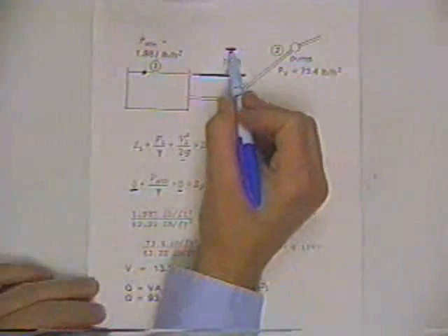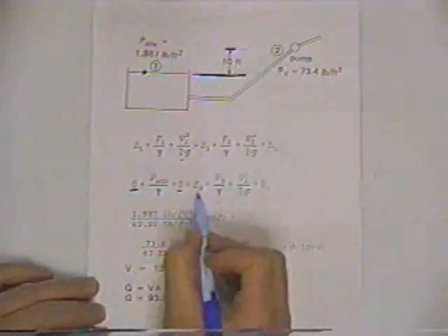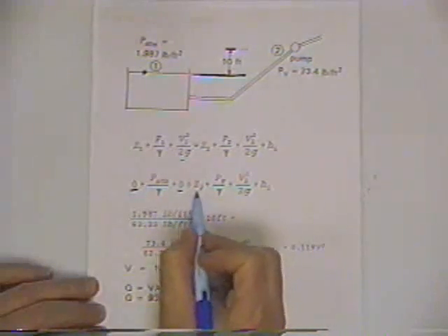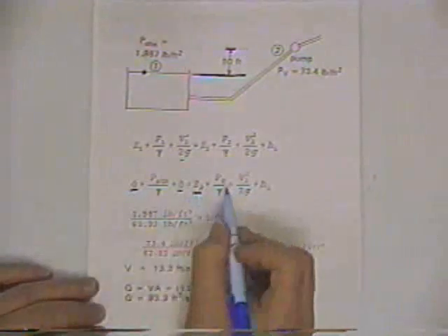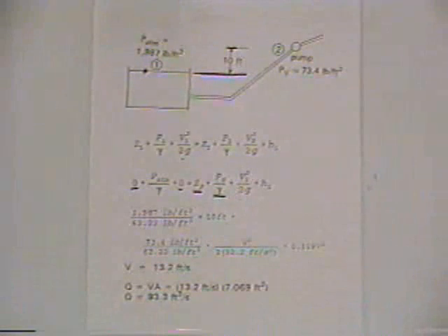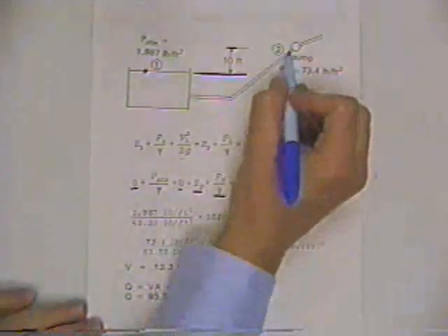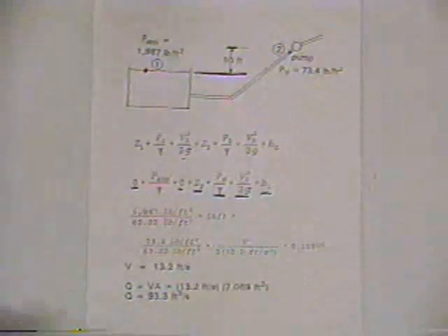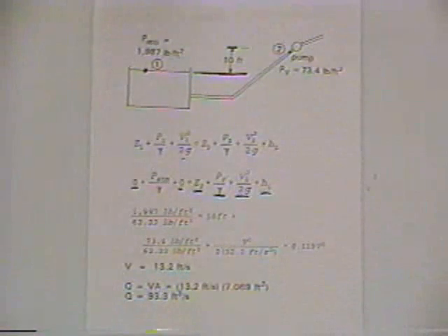Now, just generically, we could call the height at which the pump is vertically located above the sump Z sub P, and we're going to set this pressure equal to the vapor pressure. The reason we're doing that is because we're recognizing the physical situation that we don't want vaporization to occur. So that's part of the statement of the problem. And then there will be a very definite velocity of flow here, and that's the velocity head. And we've got a head loss, which the Darcy-Weisbach equation is going to take care of for us.